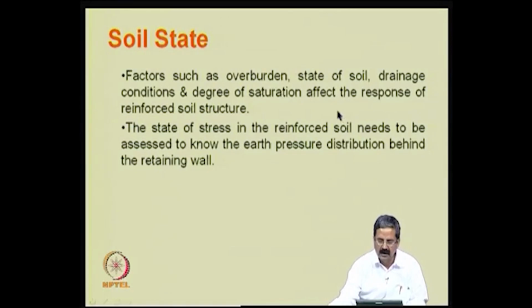So, overburden is an important factor. The state of the soil, whether it is in an active state or a K naught state, is another important factor, because it depends on the type of reinforcement also. Stiff reinforcement, as you have seen, needs very minimum strain.